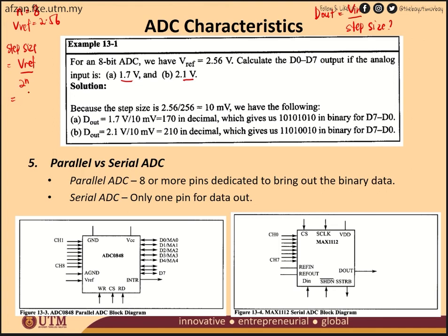VREF is 2.56 volt divided by 2 power of 8, which is 256, and you get 10 millivolt. So this is your step size: each bit here is 10 millivolt.